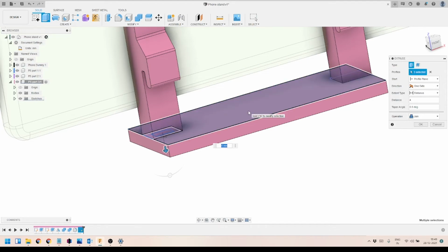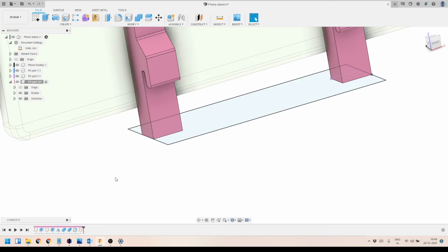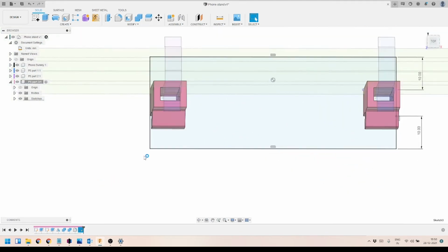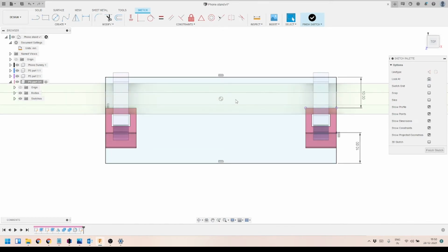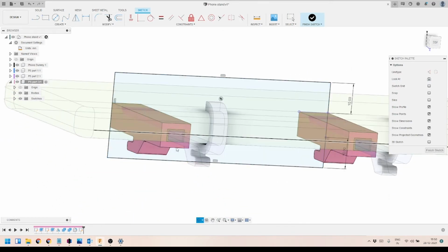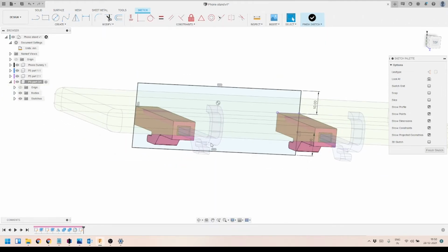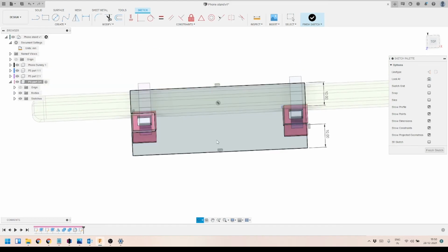Before doing that, I also want to create a hole sketch. So I will go back to our sketch, right-click on Edit Sketch, and create a hole over here, because we had a hole, right? So we'll check the hole. The hole is towards the rubber band holding area, so we'll make those holes in this direction.